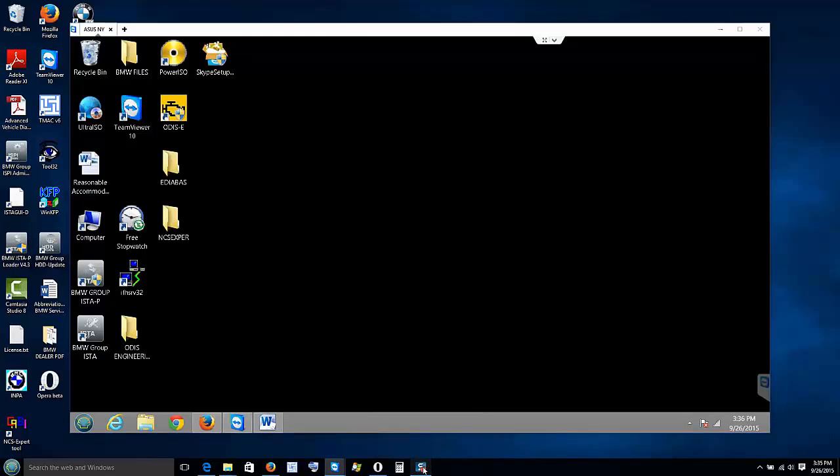Okay, this one is the DSC on an E39. We replaced the unit and did a steering angle sensor calibration, and we also did a lateral transverse calibration, and an angular calibration, and we also did an end of line test to remove the three lights from the dashboard. So I think it took us this long to accomplish it. So this is just a basic tutorial of how to repair those systems.